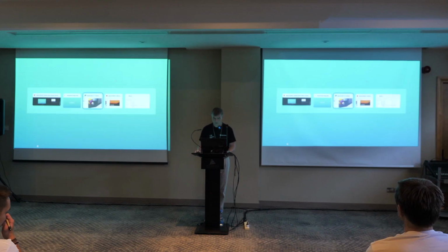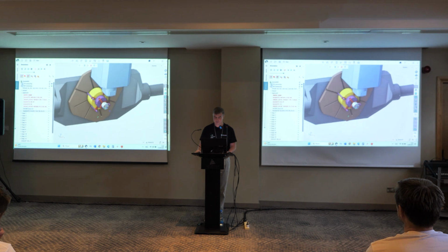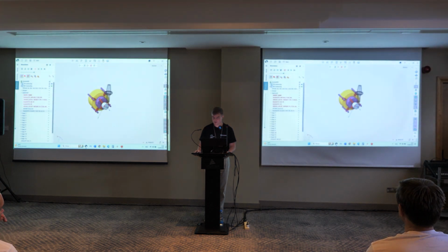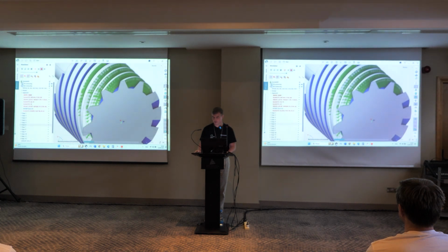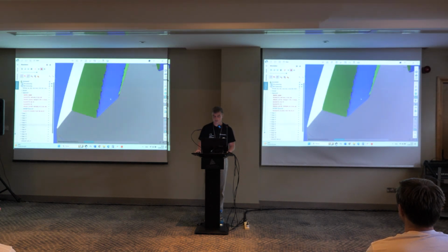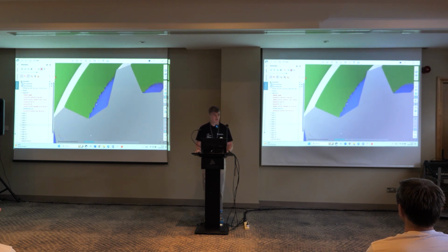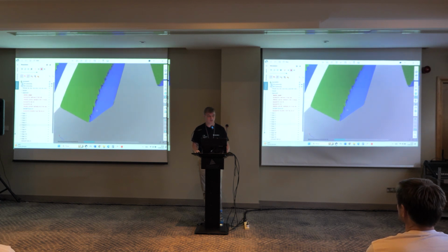I will use the same project, disable machine visibility. It's not actual here right now, and tool holder also. And in the beginning, right now we have the type of simulation voxel 5D. And let me start the simulation. And very fast results, and let's check the quality of the part. So we can see its tolerance is enough, but it's not really perfect right now.